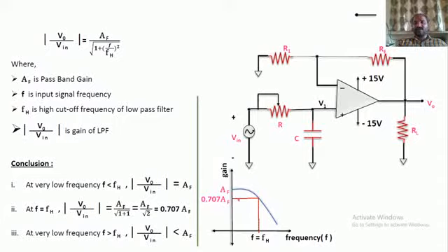From that point, draw one perpendicular line onto the curve, and from there draw onto the x-axis. At the point where the line touches the x-axis, you will get the practical cutoff frequency of your low pass filter. So without having the R and C component values and having only the graph, we can easily calculate the cutoff frequency of your low pass filter.